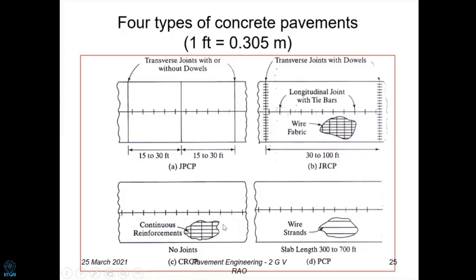So this is a continuous reinforced concrete pavement. So there are no joints at all. The reinforcement is continuous. It's like a concrete slab resting on the ground. And some people prefer it because any joint, if you don't maintain it perfectly by putting proper bitumen and other things and maintaining the spacing between them, you jump over that.